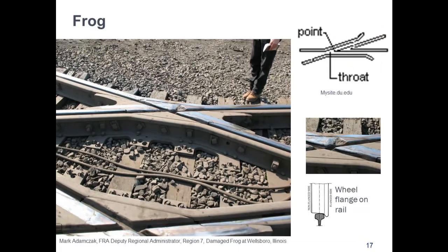So, Dick, are frogs considered special track? Yes, they are custom built, cast of manganese steel, a very strong, high quality steel, and literally in the case of a frog at a diamond crossing like shown above, they are calculated not only in degrees but minutes and actually seconds of an arc.